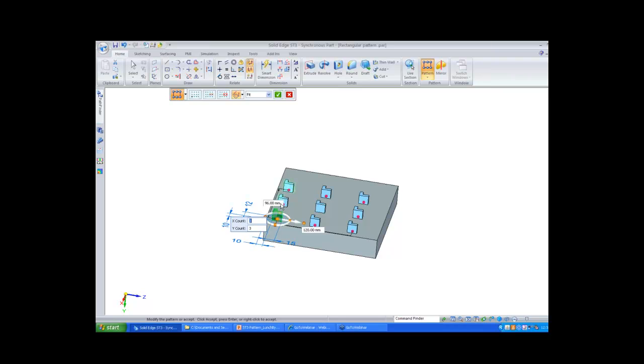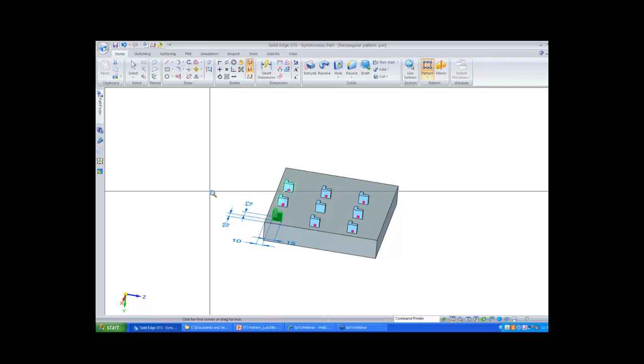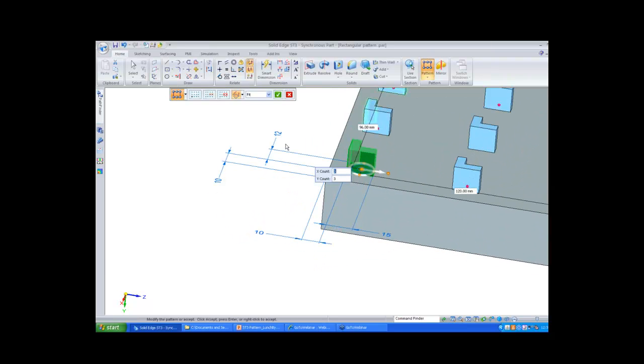And also you'll see this 96 by 120 millimeter, that's the dimension. So how does Solid Edge calculate this dimension? Let me zoom in a little bit. And now you'll see that the feature has two dimensions on it. The one is 12 and the other is 15. The way Solid Edge calculates these X and Y dimensions is it multiplies the linear outside edge of the feature by 8. So 12 times 8 is 96, that's why you see 96 on this side, and at the same time if you multiply 15 by 8, it gives you a value of 120.